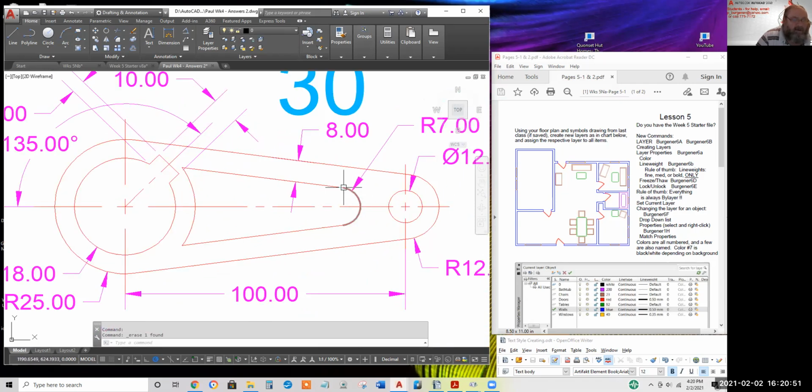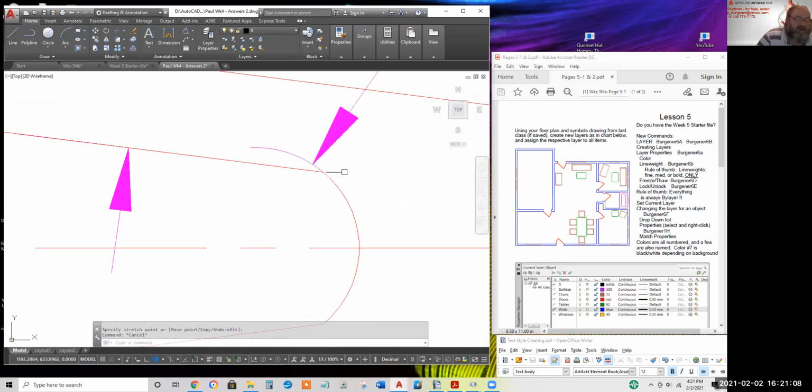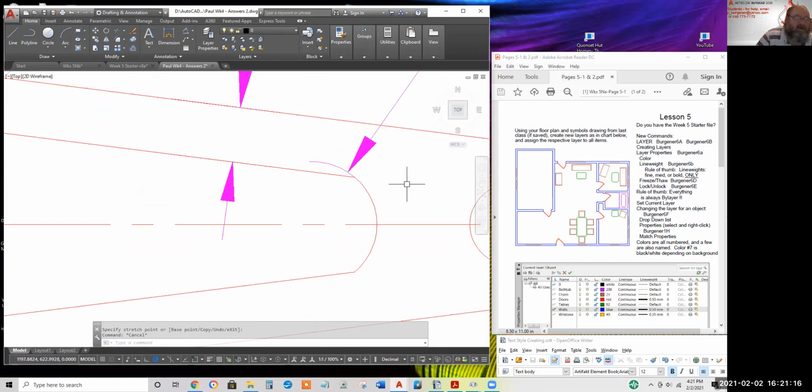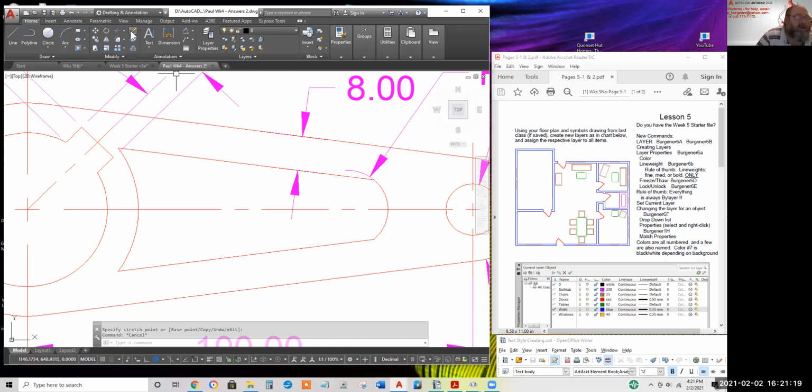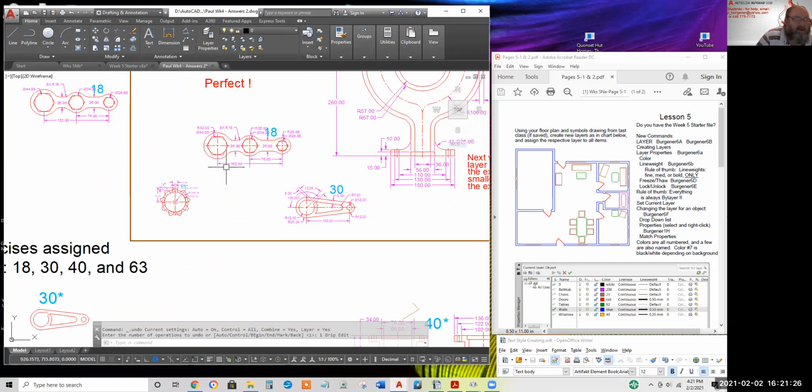Let's see, a couple of you, I think, instead of doing a fillet here between the two diagonal lines, you tried to draw a circle with tangent radius, and it came out looking with kind of sharp edges. Right there's a sharp edge. You had a circle and trimmed it at the diagonal lines, where fillet would have been smoother. Undo it. What are other common mistakes?